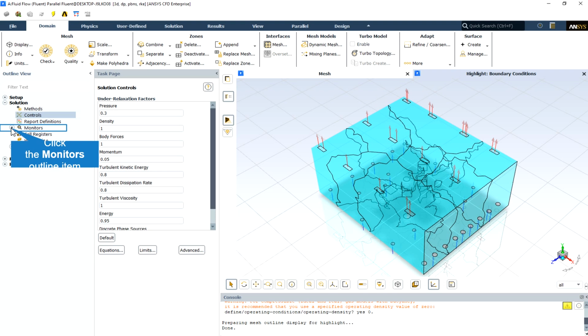This often results from increasing the under relaxation factors too much. A cautious approach is to save a data file before making any change to the under relaxation factors, and to give the solution algorithm a few iterations to adjust to the new parameters.